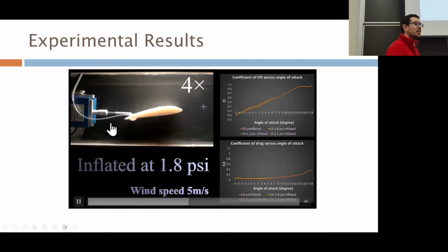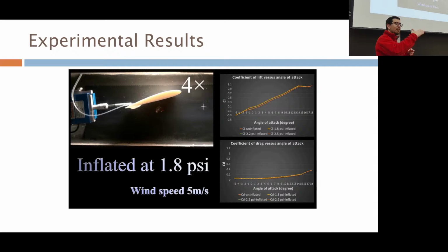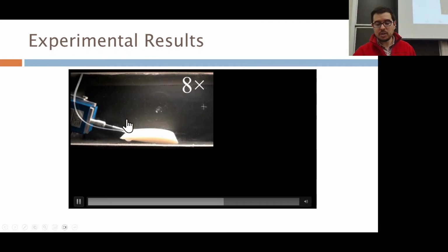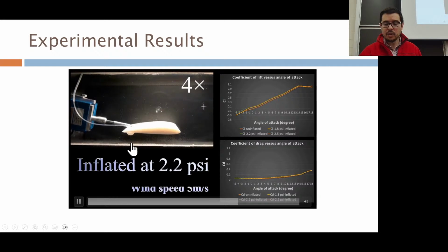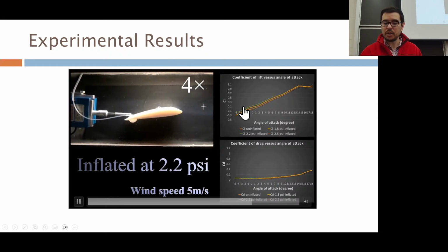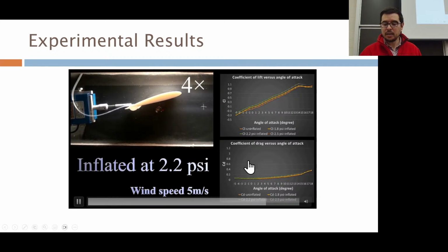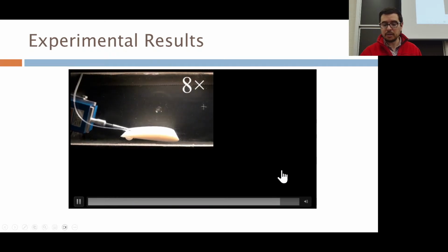And you remember when we did our simulation, we were like, hey, figure out what the focus is. One is inflated here, and you can see the coefficient of lift is higher for a given angle of attack, and the coefficient of drag also increases.